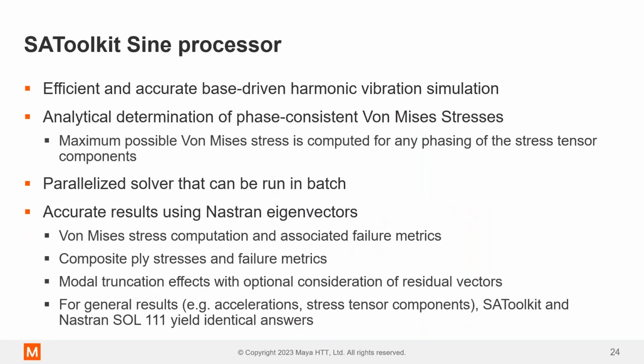Now the sine vibe processor, I apologize, these next two slides might be a bit wordy, but I just wanted to hit the main points. So the sine processor is efficient and accurate, again, base-driven harmonic vibration. It analytically determines phase-consistent von Mises stresses.